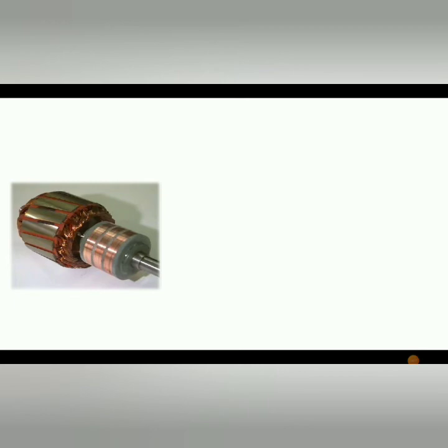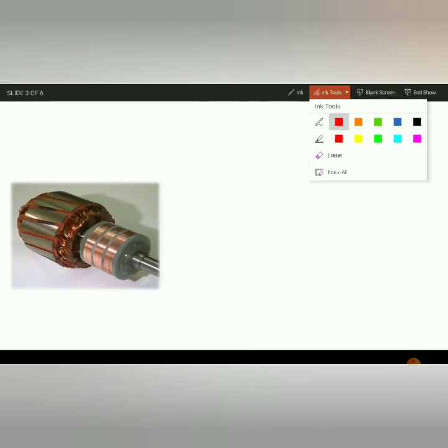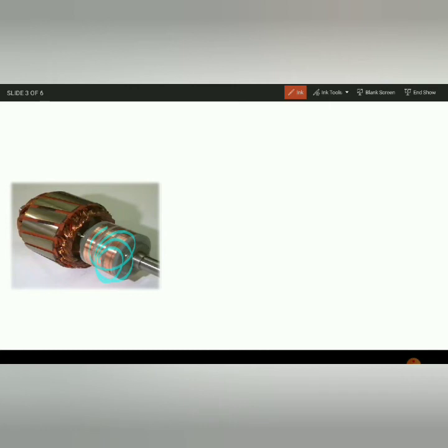See here, you can see how the slip ring looks. This is called the slip ring, and the end rings are connected. Now one more point we have to see. These are the rotor slots. We generally see them straight, but here, instead of straight, the slots are inclined. So why are they inclined? It is a very important point.